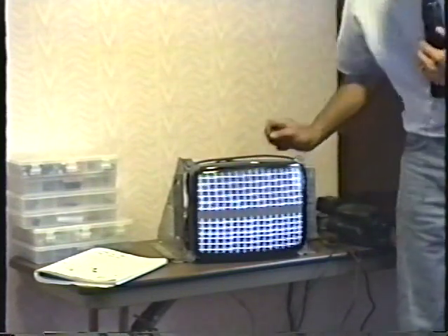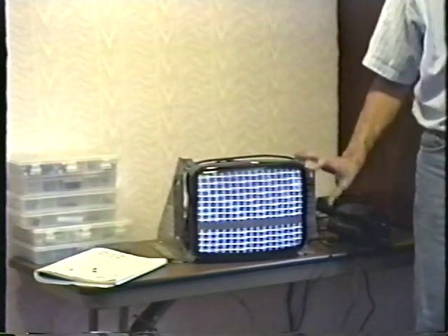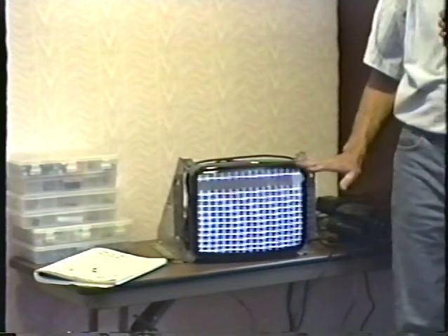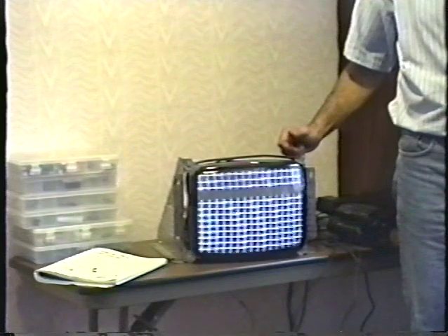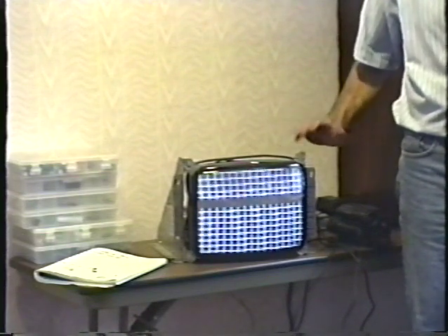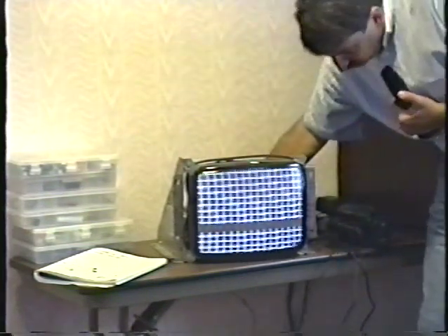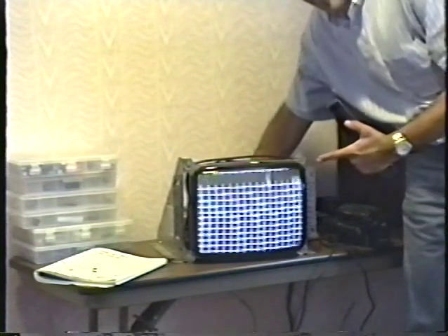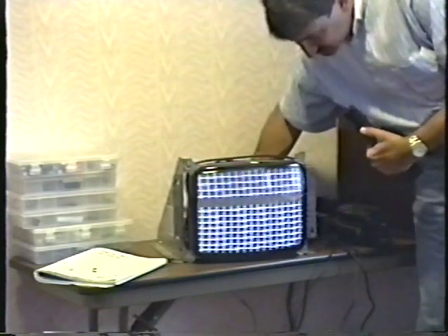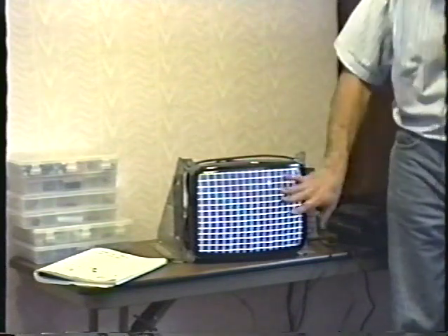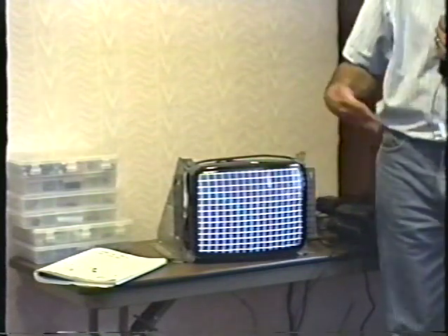But if you can get it to slow down, but it always drifts up and down and never actually locks in place, you can see this one trying to lock. If you adjust the vertical hold, you can't get it to lock in place, you have a problem with vertical sync. Not likely, by the way. These are very unlikely, but it's a part of the monitor I do want to explain to you. So when you think sync, is the picture rolling vertically? If I brought any kid in from outside and said, here, kid, fix this, he'd go for the vertical hold control and adjust it, and away you go. If you try adjusting it and it always drifts up and down, that's a vertical sync problem.